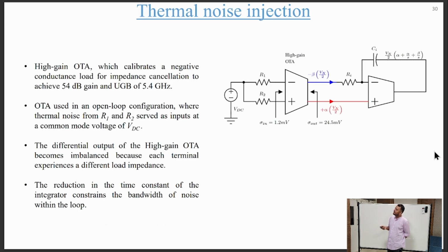Also, there is one more problem here. The time constant of the integrator is also reduced through this setup. That can lead to long chains of ones and zeros, which we solve through post processing.